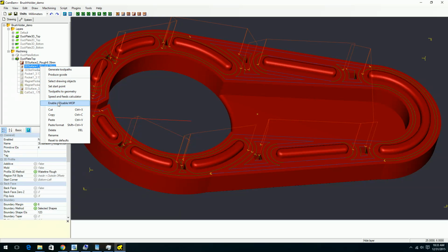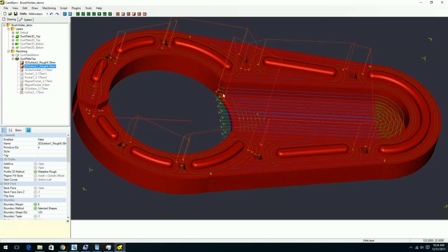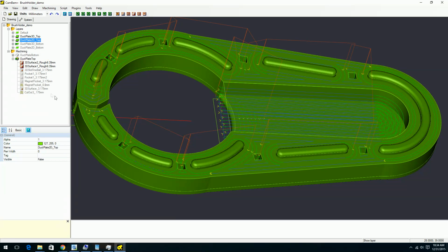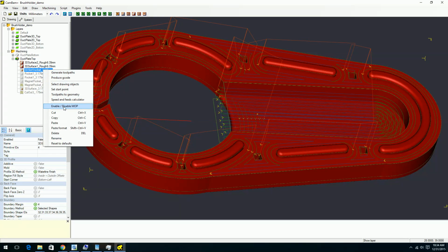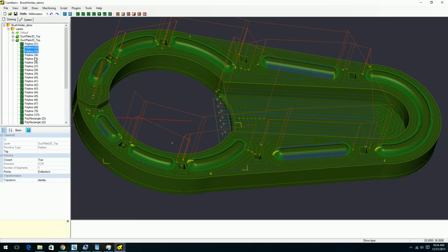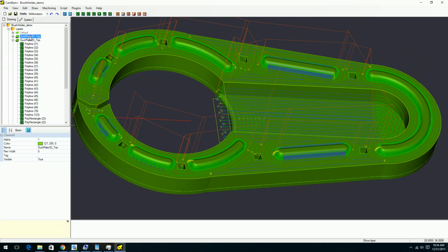You notice that this middle part that I just pointed out will not be machined, so I will have to have a specific machine operation to remove that as well. So this is the inside part that I will rough machine out. Then this will machine the ridges in a nice smooth way, as you can see here. This is a very fine machining with a ball nose bit. I'm selecting these polygons as my masks for that operation.